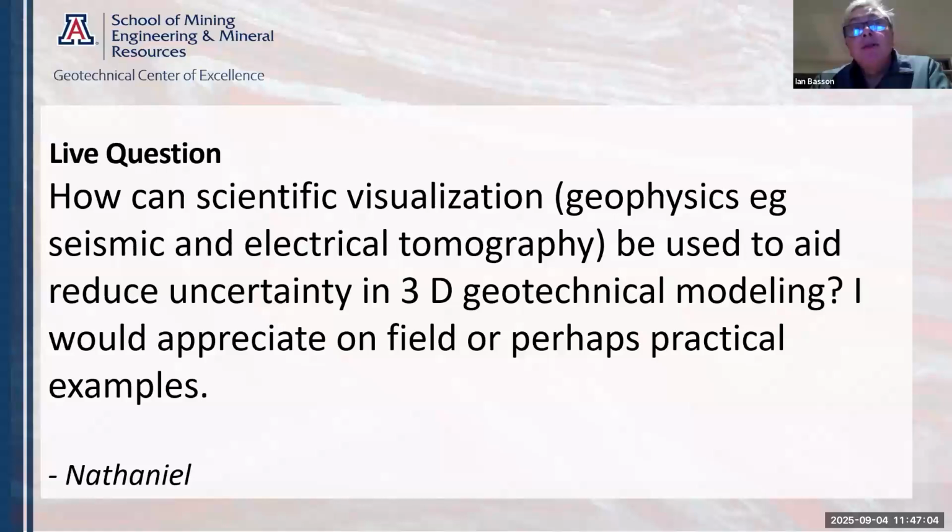The second comment about geophysics, seismics, and electrical tomography is that they've done it at a particular line spacing or data or sensor spacing, and that spacing is nowhere near the resolution or granularity that we can map at in the pit. So you can use them, but just remember that they're broad at the scale that you want to define things at when you start mining or geotechnically designing.